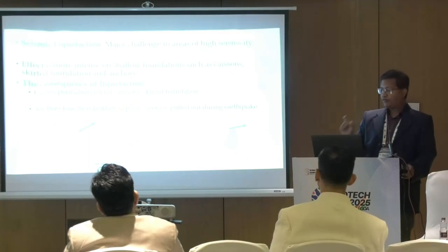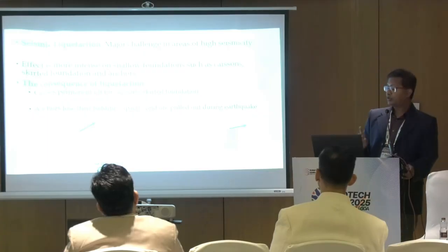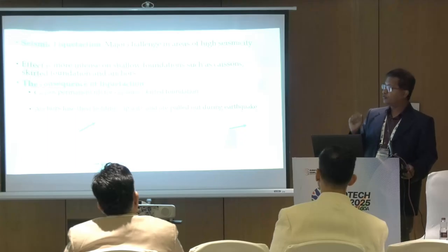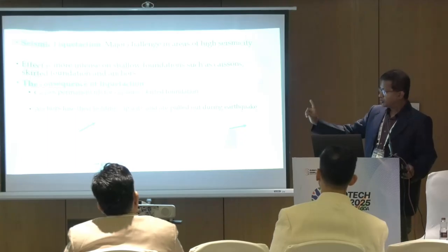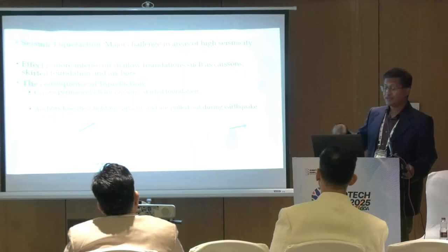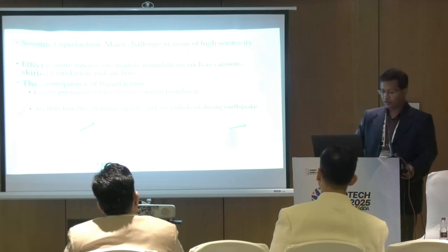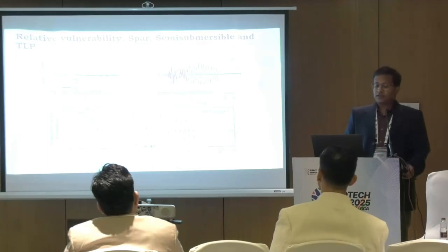And in case of anchoring system, there's one important thing that I would like to mention. Say, for seismically active areas, liquefaction could be a major issue. Due to liquefaction, the anchor pull-out capacity may be reduced, and that has also been studied, but that is not included here. So this is a typical response.